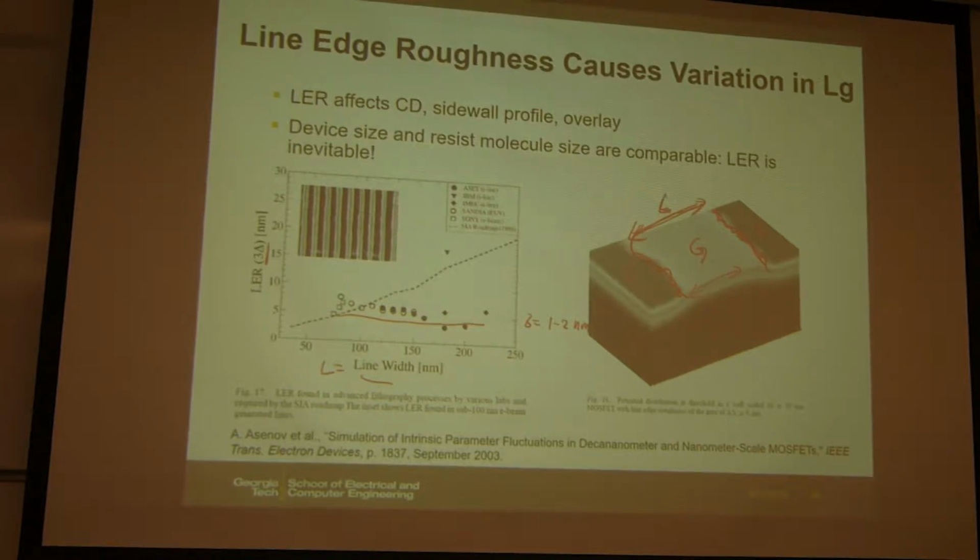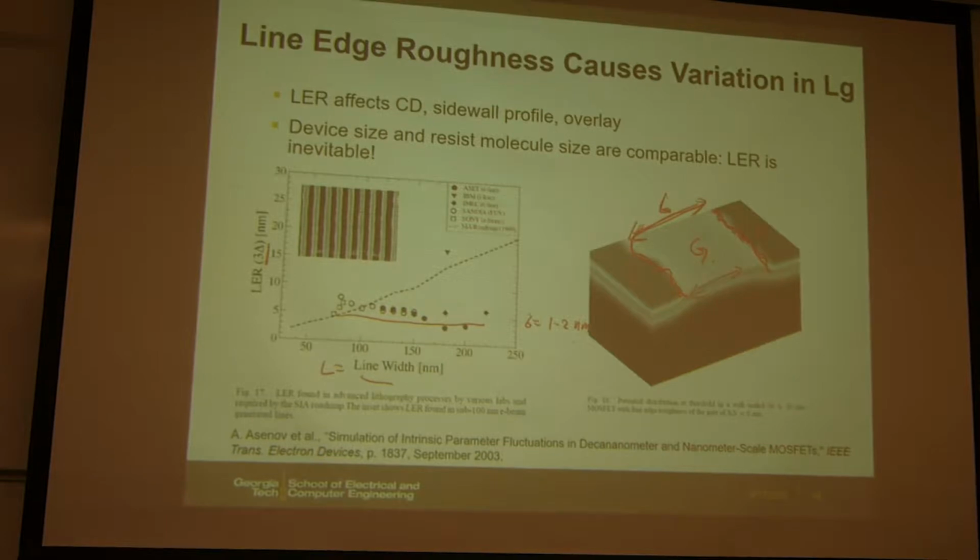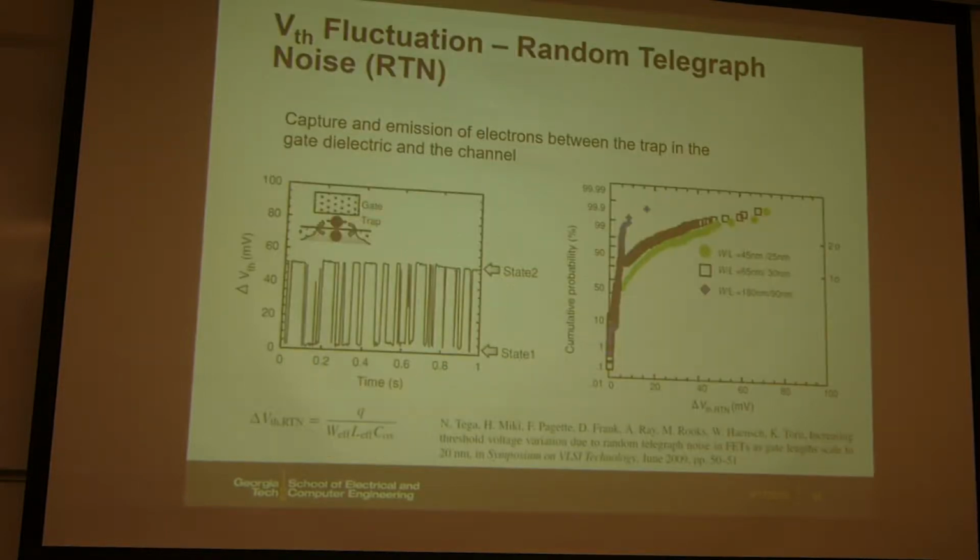So this is only one, mostly important, but all the patterns, let's say a geometry in the device, the geometrical dimensions, all of those will be affected by the roughness because of the lithography. But the L is mostly critical, because that will affect the current and the threshold voltage. So those are the static variations. Now we are going to talk about the temporal variation.